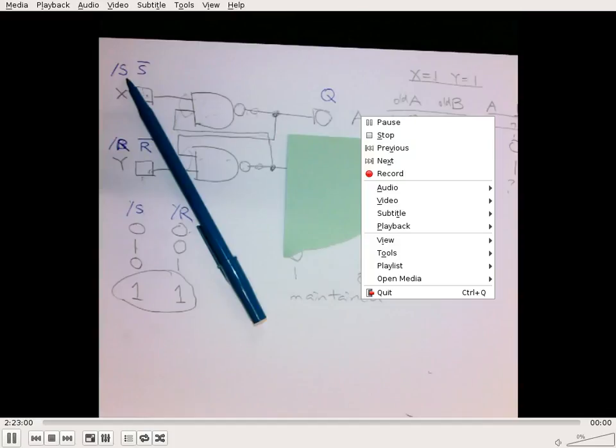So when the computer is operating correctly with healthy software components, the software component will set up a timer or some kind of mechanism to inform the watchdog and say, yep, I'm okay, do not reset. Yes, I'm okay, do not reset, and so on and so forth. Okay? And then this one here may be connected to a brownout detection circuit.